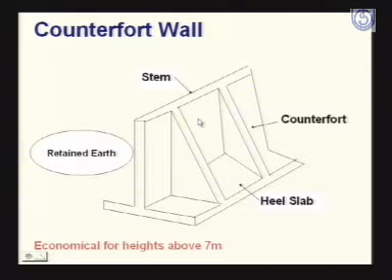So this way these counterforts help in reducing the bending moment coming to the stem as well as to the heel slab or the toe slab, thereby reducing the required size or thickness of the stem and the base slab. So this is the advantage of the counterfort wall in comparison to the cantilever retaining wall.